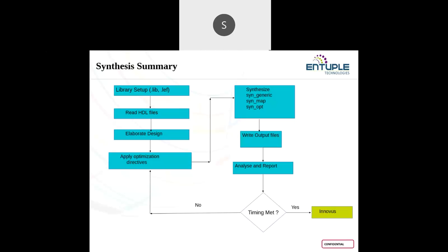So if I have a set of violations, how can I fix them with respect to setup timing? At that time I go with two cases. One is tightening the timing constraints I have written in the SDC file. I modify the constraints I have written. Another is incremental optimization.